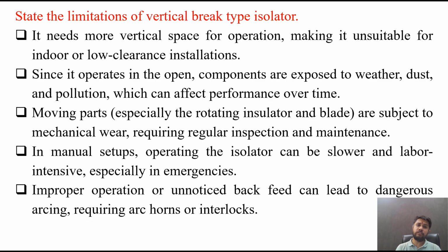It needs more vertical space for the operations. That is why it is unsuitable for indoor or low clearance installation. This low clearance means low height clearances. Since it operates in the open, components are exposed to weather, dust and pollution, which can affect performance over time. Moving parts, especially the rotating insulator and blade, are subject to mechanical wear, requiring regular inspection and maintenance.